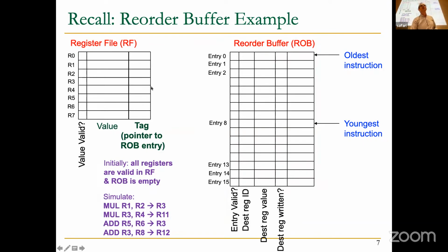And this tag can be used to communicate the readiness of a value. So for example, if an instruction that's producing R5 has a tag 16, reorder buffer entry, well, it doesn't exist over here. Let's say tag 14, reorder buffer entry 14. It can say, I'm producing reorder buffer entry 14. Anybody who wants reorder buffer entry 14, compare your tag to it. If it's what you need, then get the value that I'm sending to you. So this is how we're going to accomplish communication, basically. No more architectural register names. And you're going to see that soon.